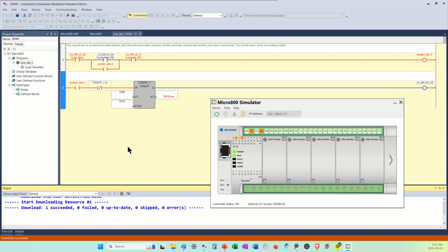Now I can adjust these times so I can make it stay on longer, or have it come on quickly and then stay on longer and then turn off quickly. So this gives you an advantage. When we used to use the free running timers, if I wanted a flashing light and I wanted it to be on for 2 seconds, off for 2 seconds, on for 2 seconds, off for 2 seconds, then I would just change it to a 2-second free running timer and it would work. In this case here, I can have it so that I can do that, or I can say, oh, I want it on for 5 seconds, but off for a second, then 5 seconds, and then 5 seconds.